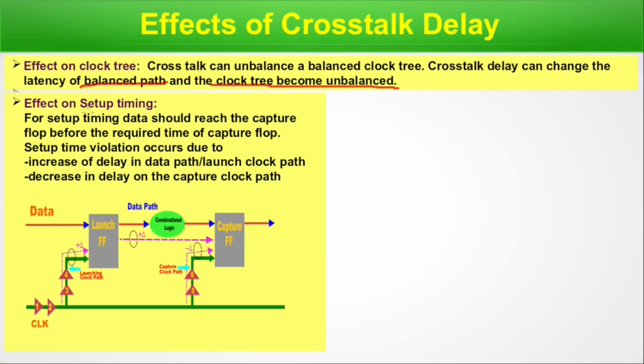Now effect on setup timing. For setup timing, data should reach the capture flop before the required time of the capture flop. There are two flip-flops. One is the launch flip-flop, one is the capture flip-flop. That is the launching clock path, that is the capture clock path, and this is the common path. Suppose here there are some cells and drivers. We have shown that with 1, 2, 3, 4 and 5, 6.